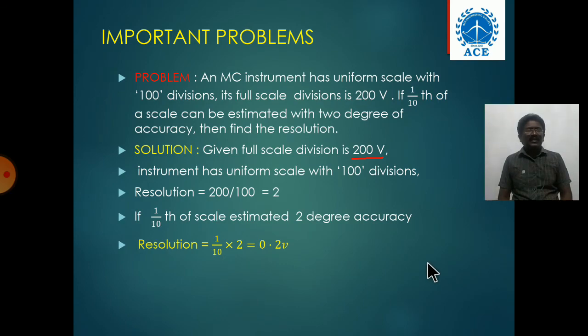One resistance will act as a multiplier resistance, the other one is a variable resistance. Across the terminals AB you can connect the unknown resistance, which is our required intermediate resistance. That means with the help of an ohm meter, you can measure unknown resistances under different conditions.